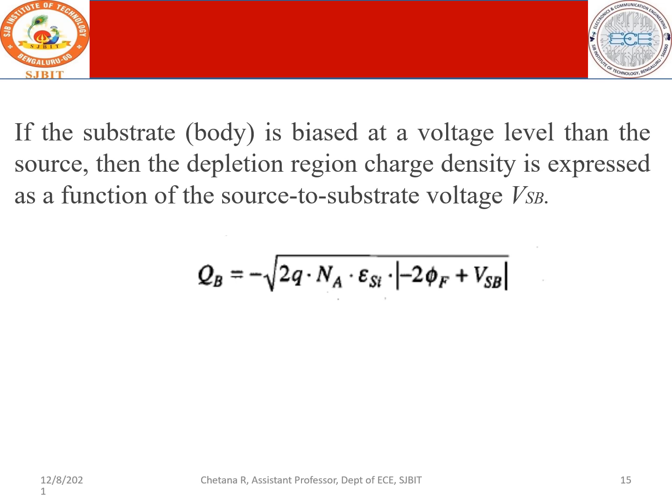But in spite of that, in case there is a possibility that the substrate is biased at a voltage level different from the source, we should consider the effects of the substrate bias, which is denoted as VSB. You can't neglect that, because in spite of that grounding, there may be a possibility of a substrate bias being formed or a voltage existing at the substrate.